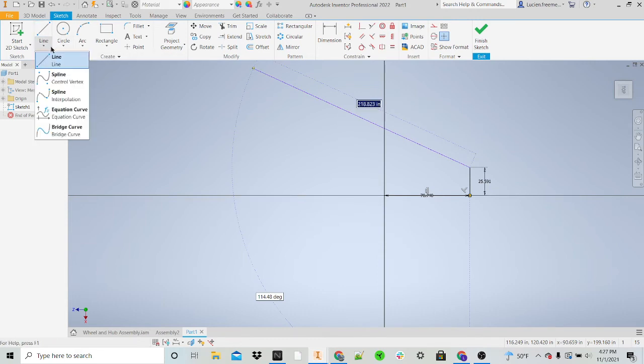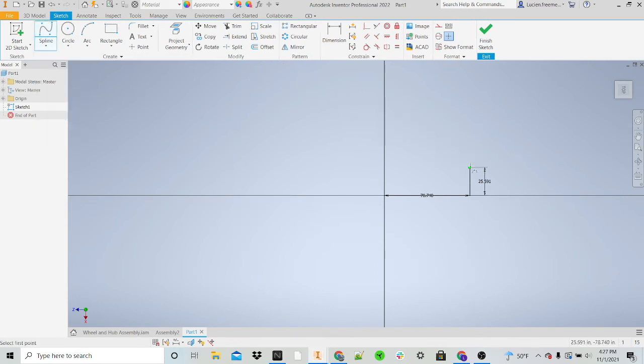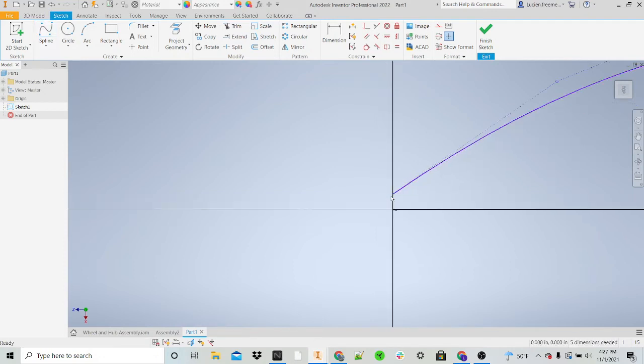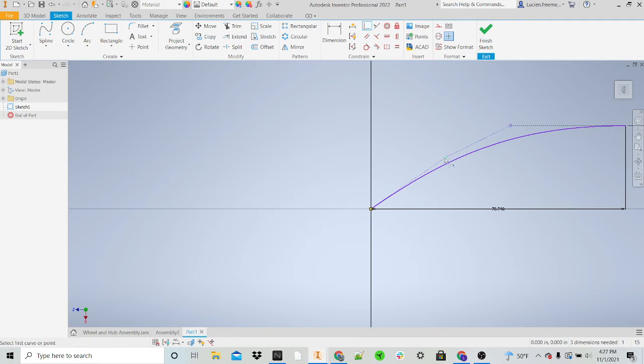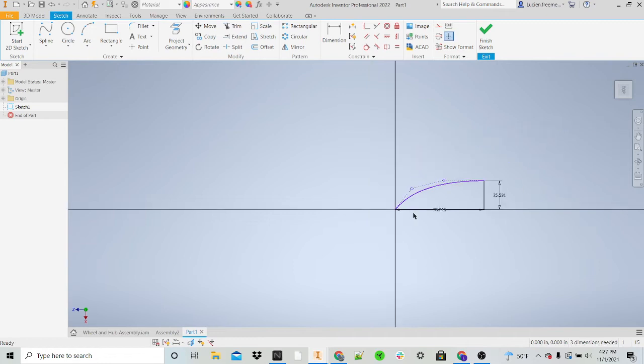Then, just to create a nice round shape, we'll use a spline, and the spline will just go from these 2 points. We like to make it tangent to that one, so when we line up the back of the car, it looks nice, and there's no sharp edges. And we'll just make sure both of these points are at the correct places, and we'll try and create a nice round shape, relatively pointed and aerodynamic, and we'll change that later with aerodynamic testing. Then once we're done with that, we're going to use that as one of our lines, and we can't have these other 2 lines in it later, so we'll just delete those.